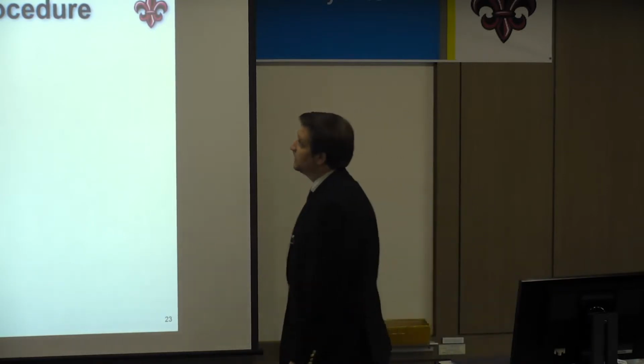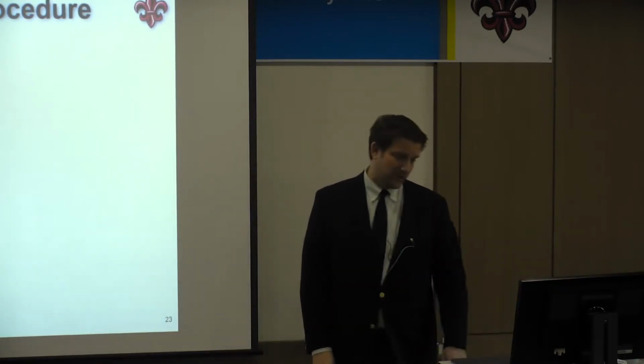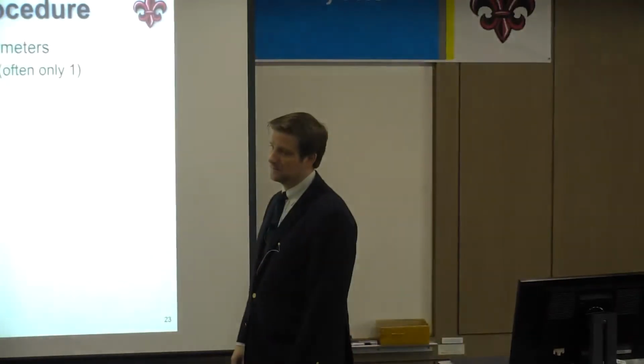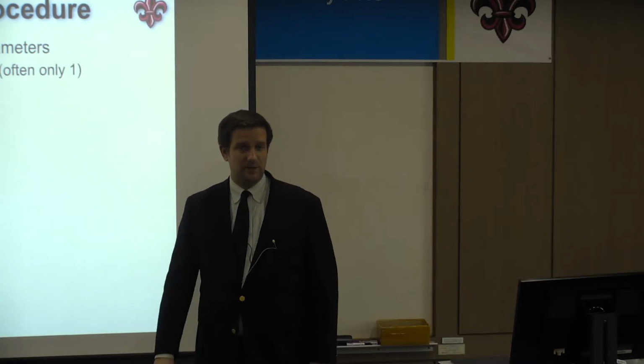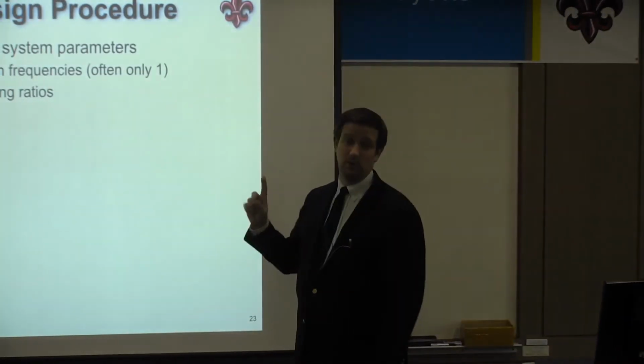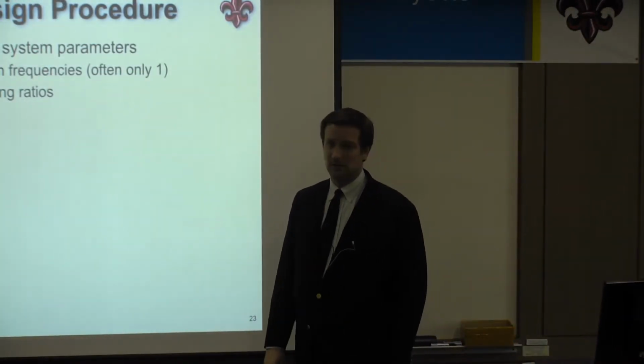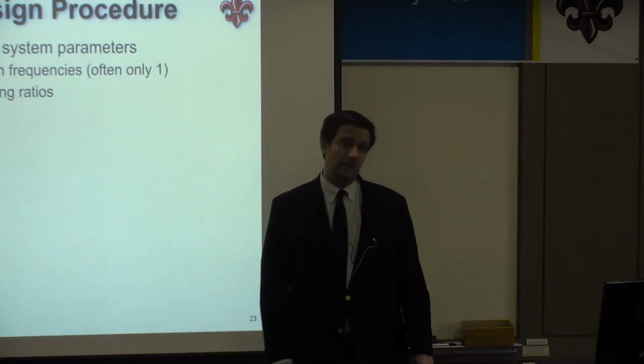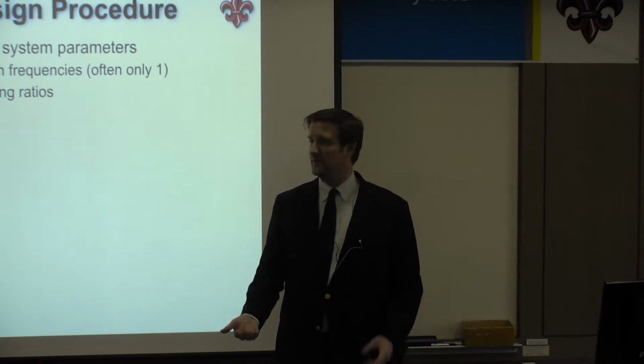The general design procedure for these input shapers is pretty straightforward. Basically, you need to determine your nominal system parameters. What are your dominant vibratory frequencies? Quite often, there's only one mode that really matters. Sometimes there are more. And then you need to know your associated modal damping ratios as well. So you need to know natural frequency and damping ratio.